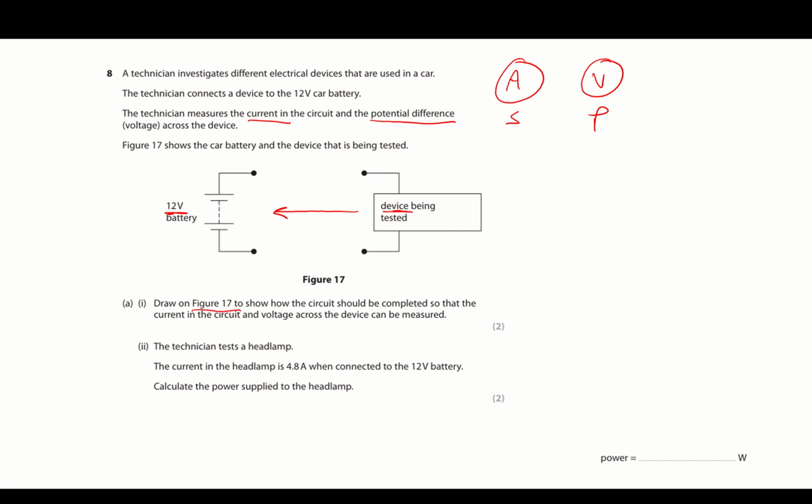Draw on the diagram to show how the circuit should be completed so that the current and the voltage can be measured. So if I was to just connect that up now, I can now see, well, I need to put an ammeter in series and a voltmeter around the device.